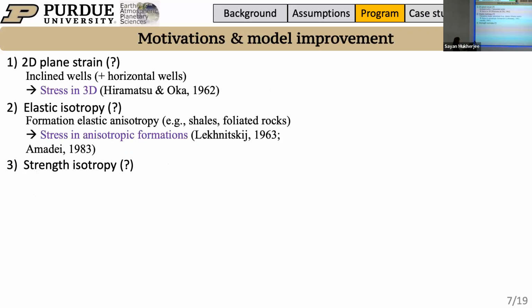But recently, due to the peculiarities of the inclined wells and also the horizontal wells, the out-of-plane stresses will contribute to the stress concentrations. So we need to know the stress in 3D, and also, as I mentioned before, for the shales and also for the foliated rocks, we will have elastic anisotropy. So we also need to understand the stress in the anisotropic formations.